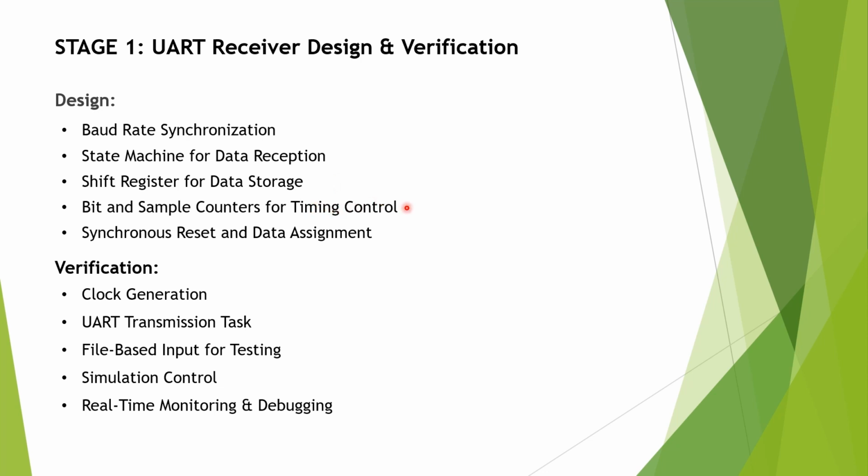Next are the bit and sample counters for timing control. The bit counter counts the number of bits received, and the sample counter will ensure correct sampling within each bit period to improve reliability. Basically, the sample counter ensures when the sampling of the data is to be done.